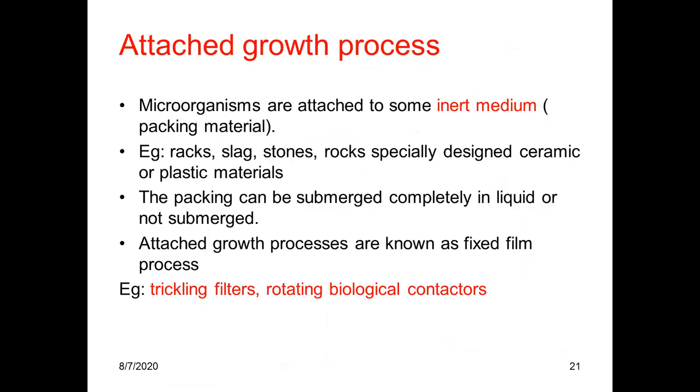Then let's see what is attached growth process. In attached growth process, microorganisms are attached to some inert medium. That means there is a packing material. Now you can understand in suspended growth process, microorganisms are suspended in the water. But in attached growth process, microorganisms are attached to some inert material.